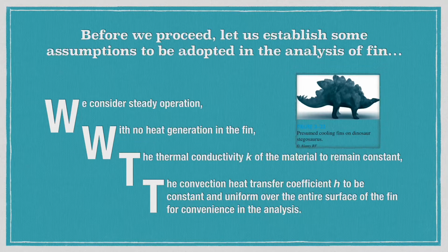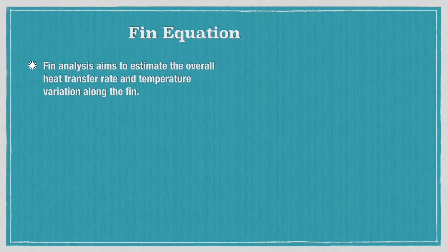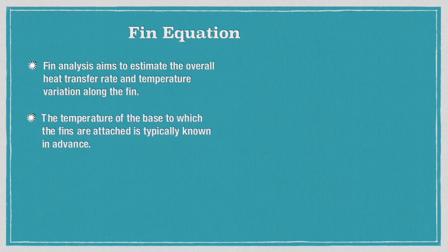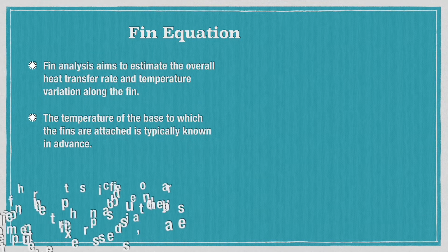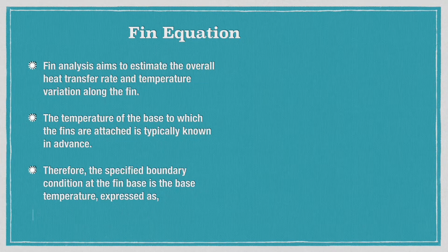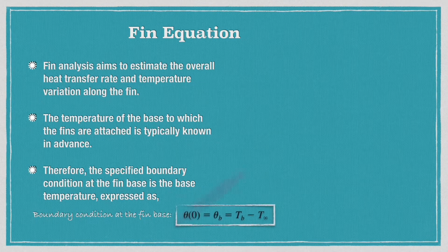Fin analysis aims to estimate the overall heat transfer rate and temperature variation along the fin. The temperature of the base to which the fins are attached is typically known in advance. The boundary condition prescribed at the fin base is a specified temperature, as shown in equation 3-59.